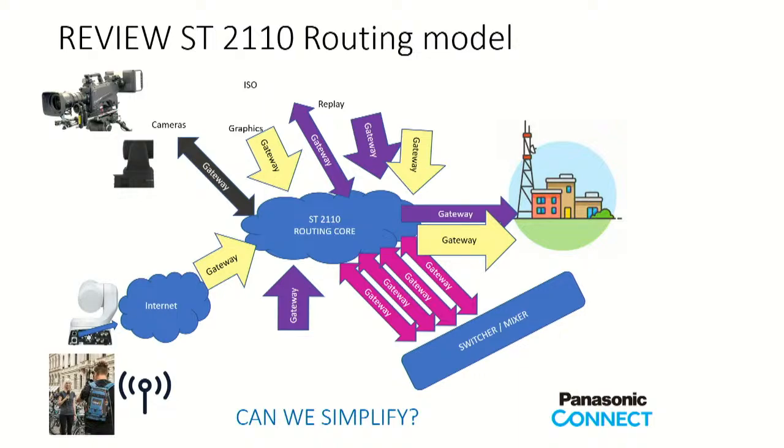So it does have NDI also on the same network, but people prefer ST2110 because you can have a return video on it too. NDI is always one way from the camera to the device. It can communicate for the control part of it, but that's about it. Whereas with ST2110, I can send a video from the routers back to the camera, a return video on my PTZ.